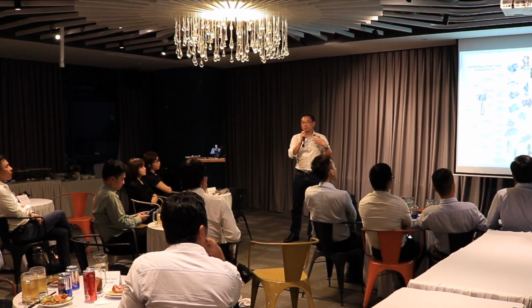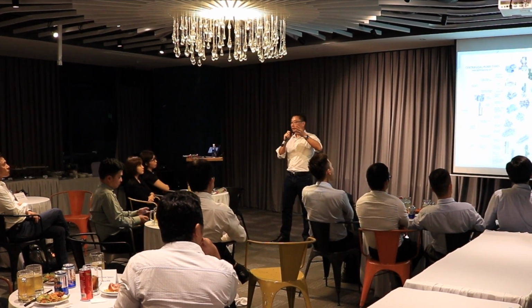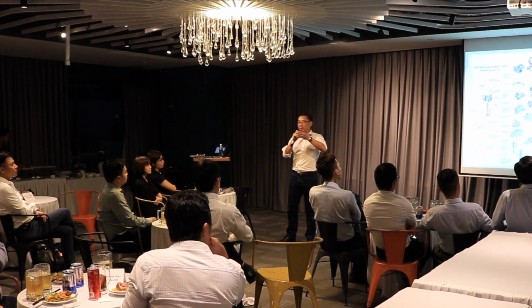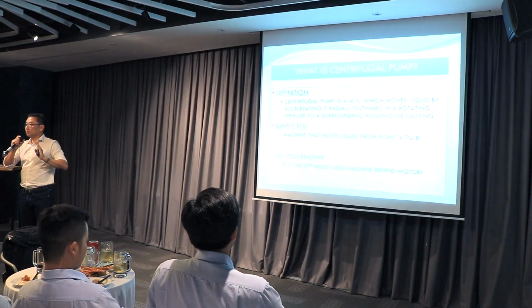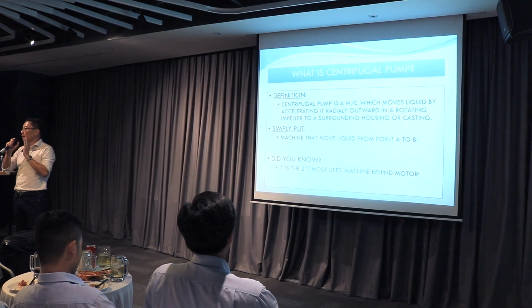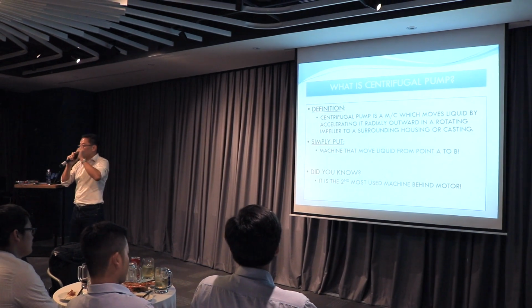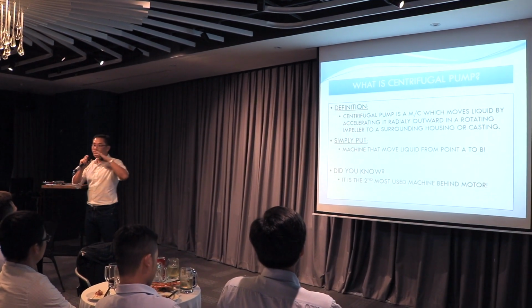So in the pump industry, you normally classify pumps as OH, BB, or VT. OH, overhung design, BB, between bearing design, VT, vertical turbine. But pump has not changed design for the past 50 years. Has not changed. Material has changed, and the process of how to make a pump has changed.